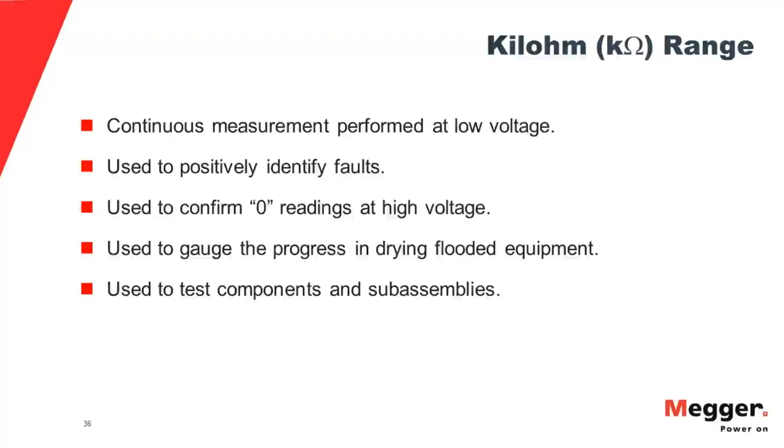And it's a very good feature in something like drying out flooded equipment, which in certain parts of the country, of course, and we've been hearing a lot of this in the news over the last few years, this is huge. Equipment that has been underwater does not necessarily have to be replaced. It can be reconditioned. Drying it out is very important. And you can use your kiloohm range then to see what kind of resistance reading you get when it's flooded, and then periodically check it as you're drying it out and see that it's improving up until you get into the megohm range.